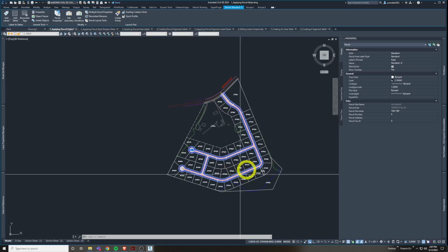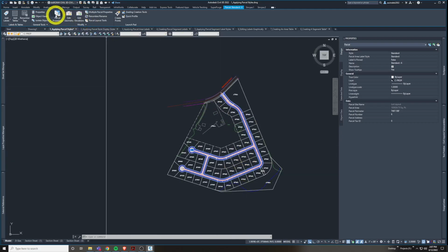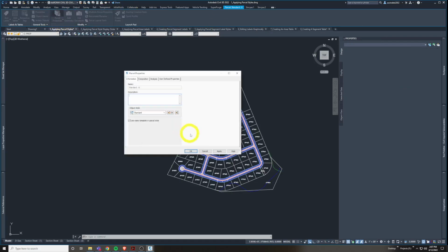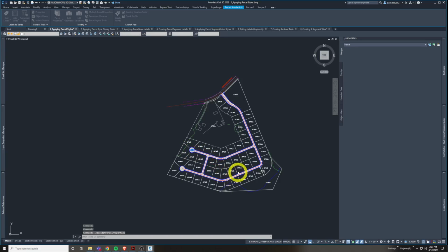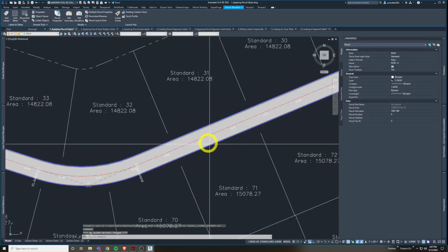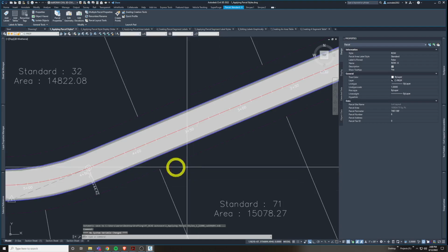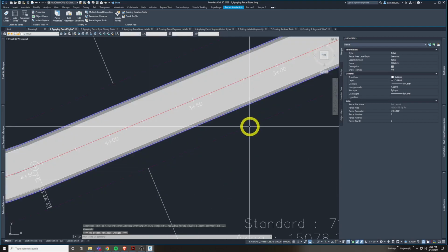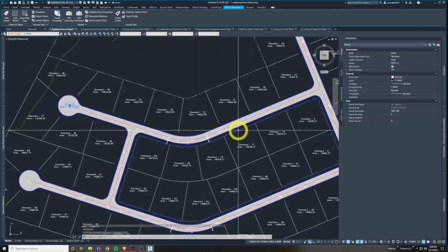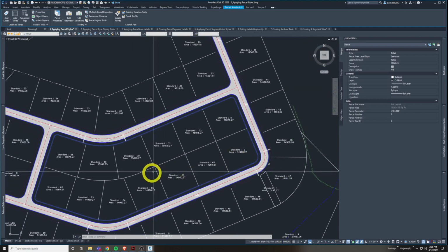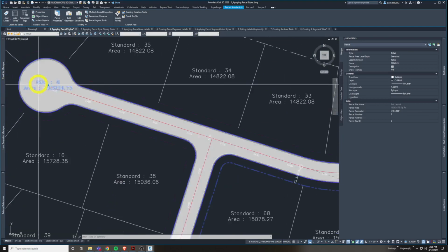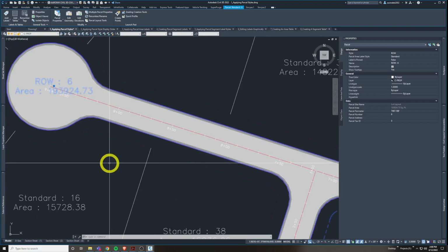And in this case, let's go to change it this way. I have it selected. As you can see, my selection set parcel is the only thing selected there. I'll go to properties up here just to bounce between, getting used to that. Let's change it to the right-of-way parcel object style. Okay. Its symbology changed to a magenta, barely distinguishable phantom line there. It's hard to see with the black. And its label probably changed as well. There's its label. Gives its full area and square footage.